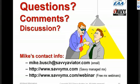And there tends to be a natural tendency, both on the part of mechanics and aircraft owners, that if an alternator ceases to charge the battery, to just assume that the alternator is faulty, when frequently it's not the alternator's fault at all. And as I try to point out in this webinar, troubleshooting a charging system is not rocket science. It's a very simple circuit, and there's a very simple step-by-step checklist that you can go through, which I tried to present several times, to determine what's wrong.